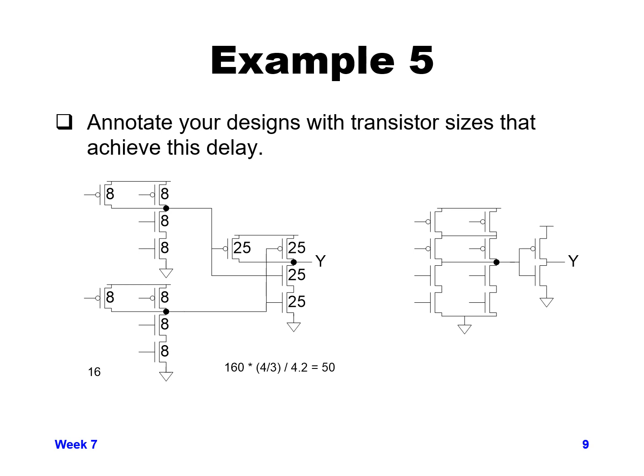We multiply it by the stage logical effort, small g, and divide by the delay that we need, the f sub hat value that we calculated in the previous slide.